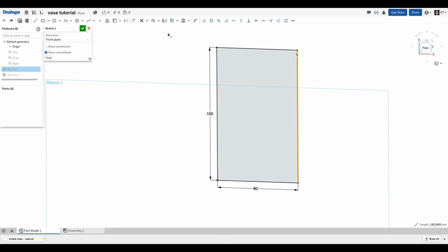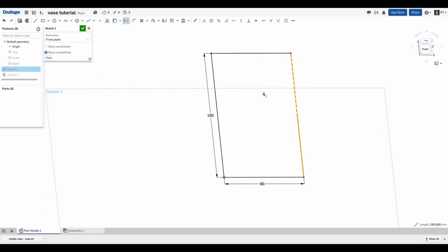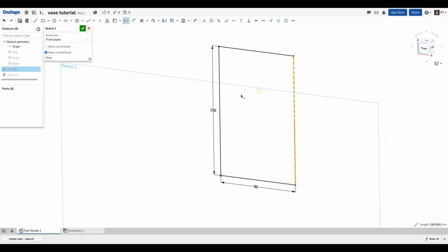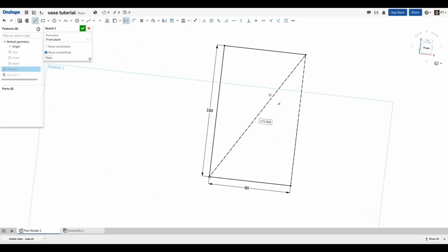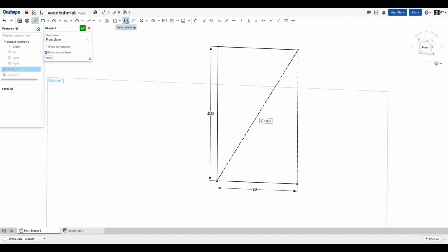I want to use that just as a construction line. So we'd use this tool here and convert it to a construction line. So this dimension would stay intact, and this shows us our constraints for working within our 3D printer's space. Do a straight line here. We could do a point to point. It's a construction line. So we need to deselect the line tool. Select this line. Turn the construction on and off. You can toggle it by clicking that or use the Q key.